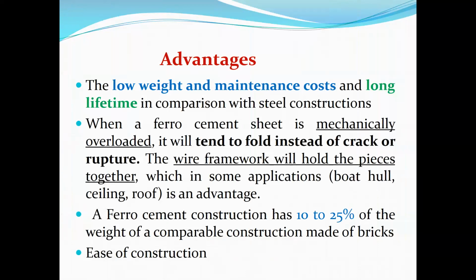Advantages of ferrocement: it has low weight, you understand, and low maintenance cost, and long lifetime in comparison with steel constructions. Here I doubt, though, those who advocate for ferrocement normally show a lot of advantages and normally hide a lot of disadvantages when they compare it with conventional steel structures or conventional concrete structures. So low weight is okay. The maintenance cost is an advantage. I'm in doubt. And long lifetime may not be, because I don't think that it will have a long lifetime, though in the slide it has been shown as an advantage in comparison to steel constructions.